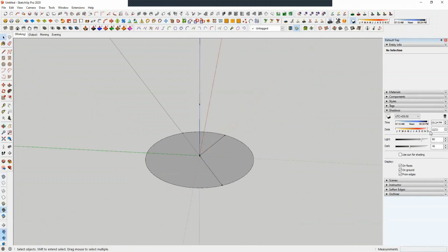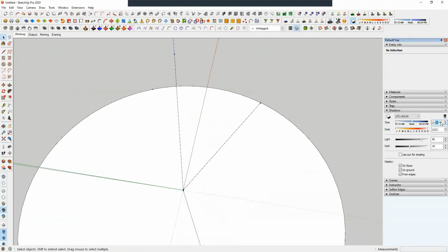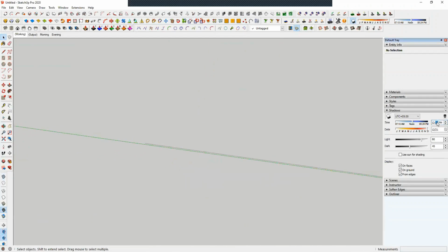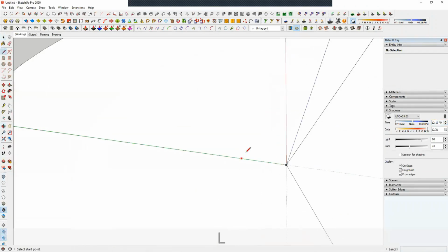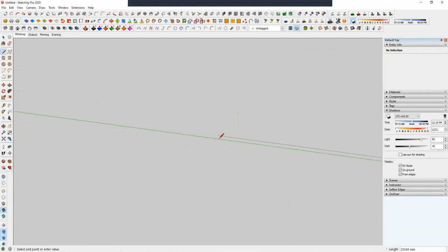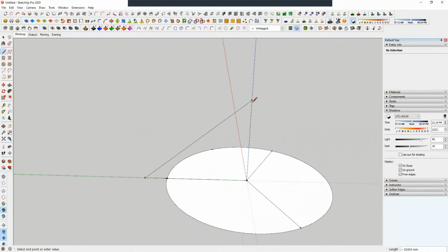So similarly, we will be finding the local apparent noon at around 12 o'clock. So it is 12:20 to, okay, it seems accurate more or less. At around 12:19, okay, 12:19, we have the local apparent noon. So let's measure the length and find the altitude angle along the green axis. Here I'm going to pick the length slightly smaller, because if we go more accurate, then this will be smaller, and pick up this point.